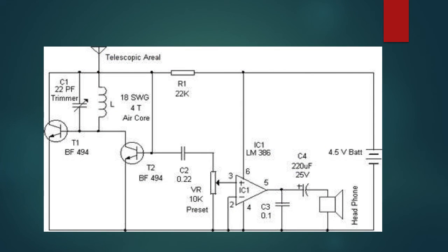Let's see. This is a circuit. An LC pair. The LC pair is used to tune in our circuits. When they are placed parallel to each other, they form the simplest tuner, where the capacitor or inductor is made to be variable. This creates a resonant circuit which responds to an alternating current at one frequency. The circuit allows switching between different frequency bands.